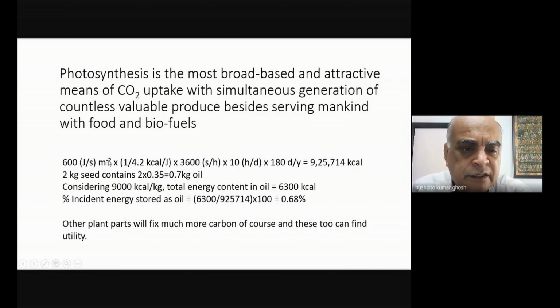That is the typical insolation, and you get your insolation for how long? In a day, let's say from something like 8 o'clock to 6 o'clock, after that it gets very weak. So I can take 10 hours per day, right? And I can also convert from joule into kilocalorie. If I want to do that, I'll divide by 4.2 joule per calorie, right?